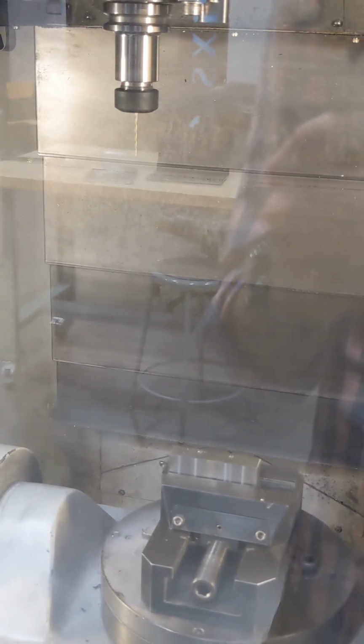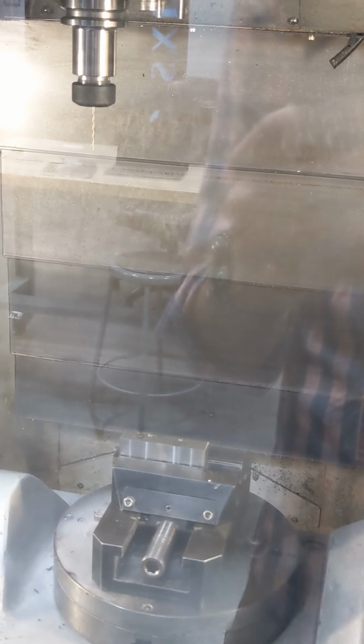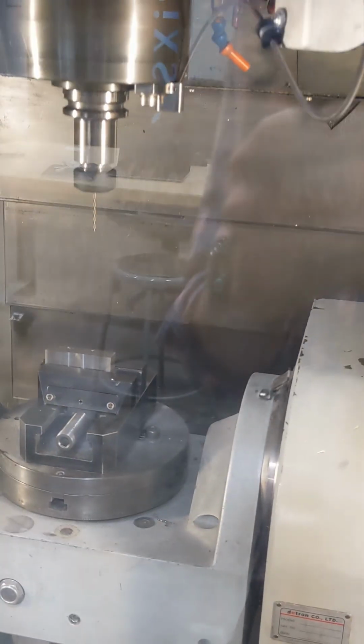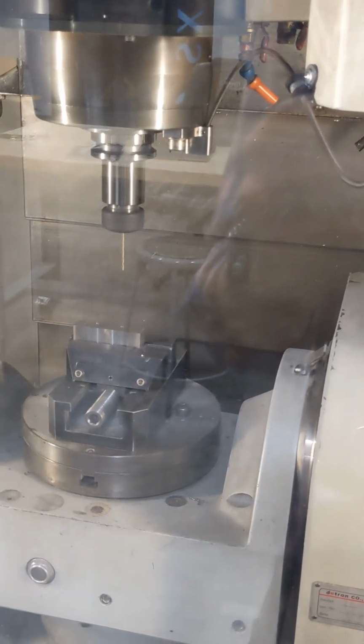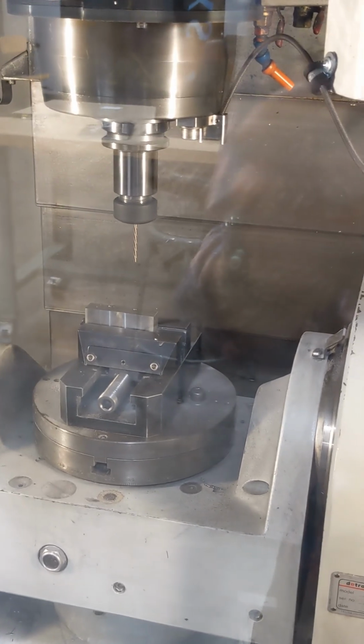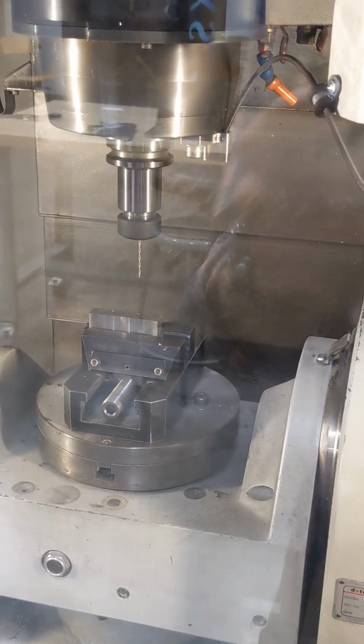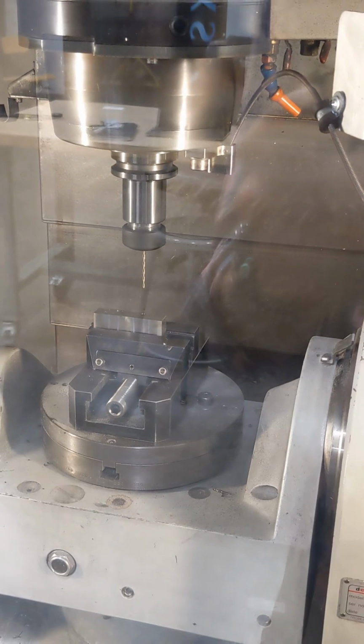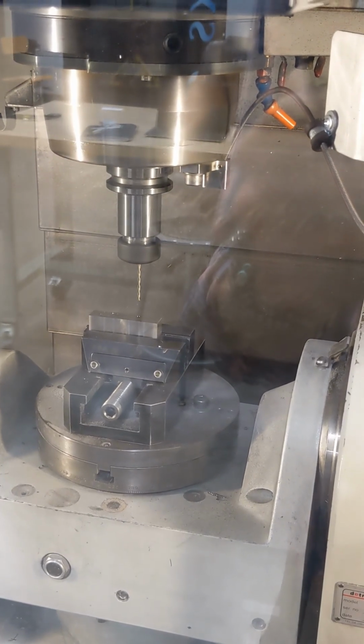Next we will see, we'll make sure this drill moves to the correct location. This is where we want to be careful. If you didn't put that tool height in, the tool would slam down into your workpiece, breaking your tool and probably your holder, and could mess up the spindle alignment.